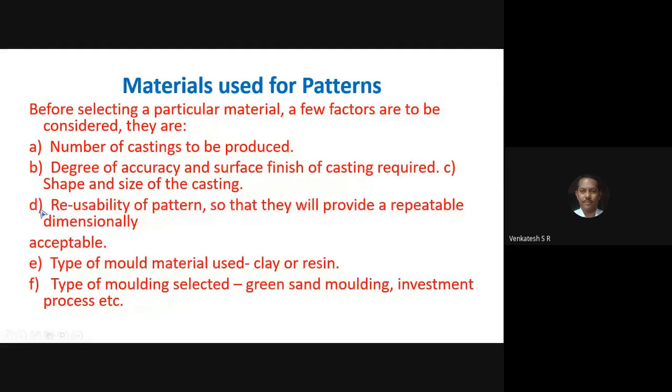Next, come to point number 4, subdivision D, reusability of pattern, so that they provide a repeatable, dimensionally acceptable pattern. That is nothing but reusability. If you use the pattern once and then throw it away, you will not get economy.